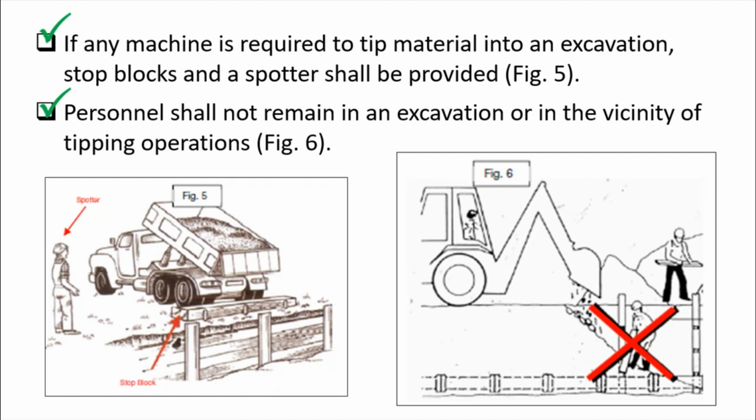Personnel shall not remain in the excavation or in the vicinity of tipping operations. So remove all personnel when we are tipping materials into the excavation, because we don't know if the moving vehicle or the excavation will collapse during the vibration.